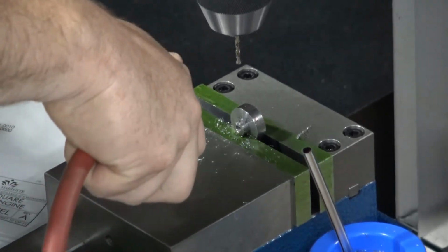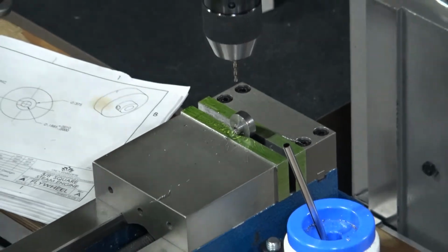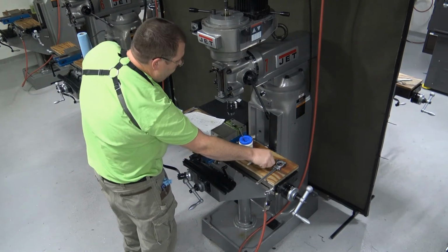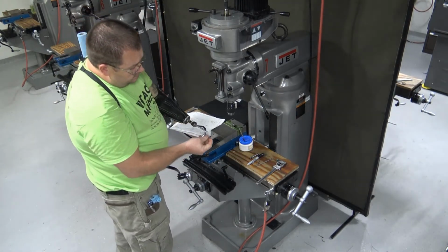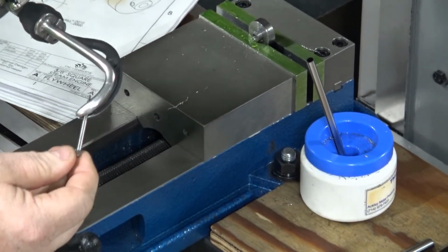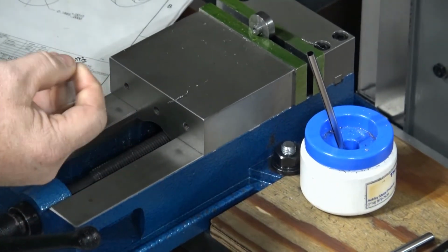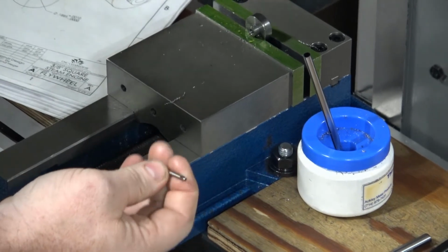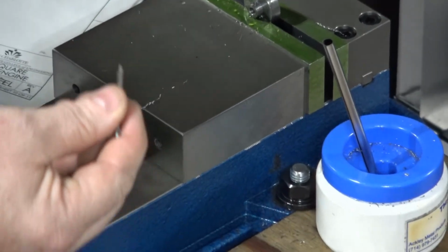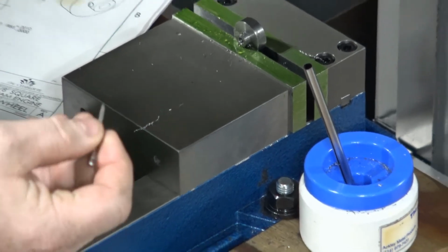So from this point forward, we're not going to run the spindle anymore. Take our drill out. This is our 6-32 tap. We can look on the outside diameter of it and see that it clearly says 6-32 UNC. There's actually a point ground on the end that you start feeding into the hole, and a cone or a point ground on the back side.